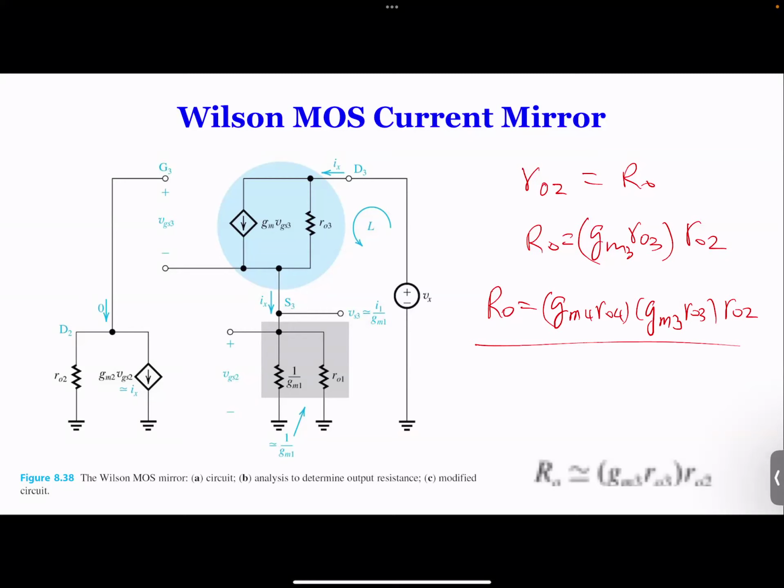So most of the time, we only need 2 stages because the resistance is already big enough, in the many mega ohm range. So we normally don't need many. Maybe one stage will increase the resistance from kilo ohm to mega ohm, and then the other one will increase it to hundreds of mega ohm. So this is where this thing is so important.